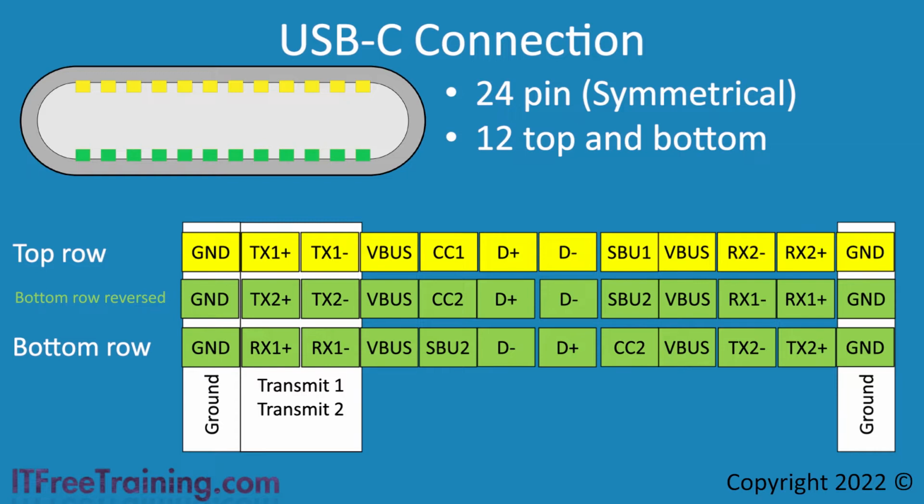USB-C uses differential signaling, and thus two wires are required to transmit. Using two wires to transmit means that both are affected by interference in a very similar way. This allows a lot of data to be transmitted down the wires at low voltage. Differential signaling is becoming very common with high-speed serial transmissions. You can see that if the cable is flipped, the top pins are still used for transmission. However, the only thing that changes is they become essentially lane 2 for any transmission rather than lane 1.